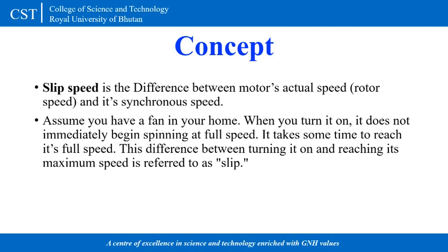On the specification we see the speed of the motor. Let's say the speed is given as 1400 RPM, rotations per minute. This 1400 RPM is actually not the synchronous speed, but rather the speed of the rotor.